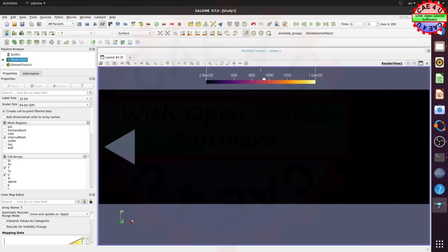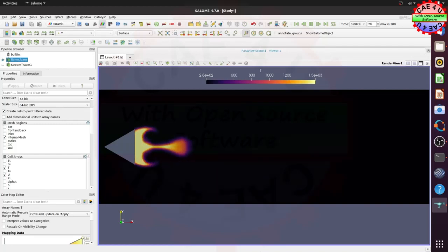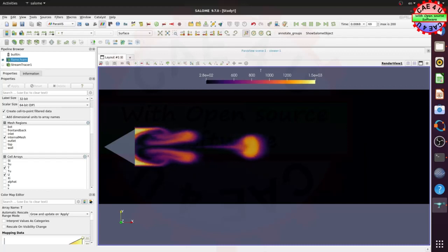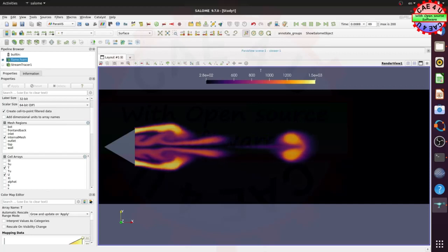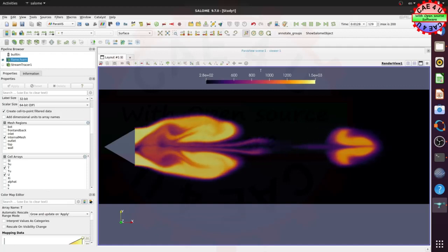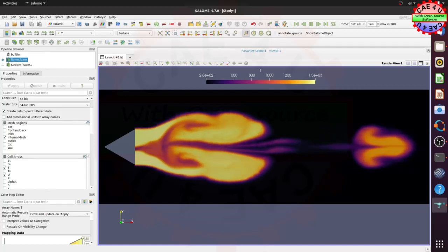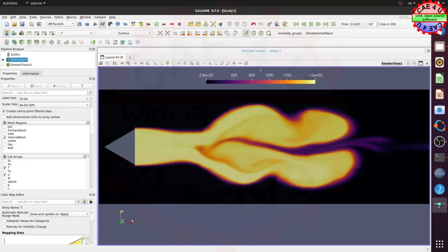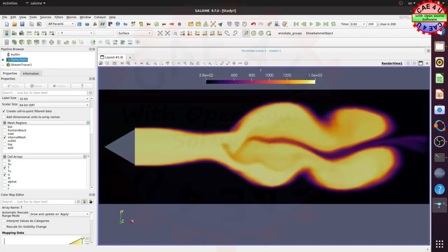Our primary objective is to look into the thermal distribution. So let us look into the thermal plot. The initial circular patch you see is the ignition patch, which was given for about 5 milliseconds. The charge catches fire and it starts burning. The evolution of the flame appears to be reasonably captured in the simulation. We could also see the shear layer instability. The combustion zone slowly increases and a larger chunk of the charge starts burning.